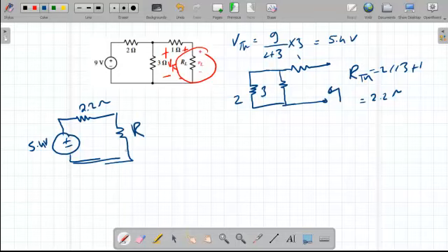So the first value is VL, which will equal 5.4 over RL plus R Thevenin, times RL. It will equal 5.4 over 3.2, times 1, the resistor. It will equal 1.6875 volt.